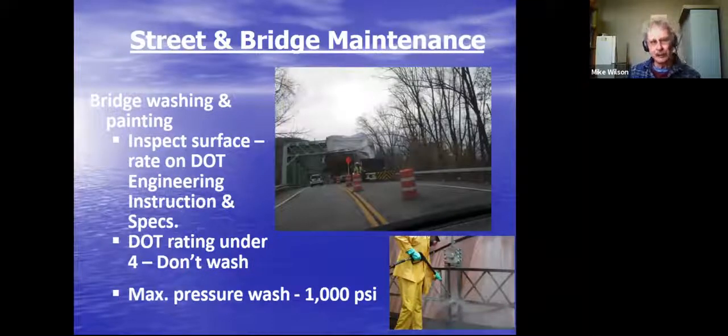Before you wash a bridge or paint a bridge, you have to inspect that surface. And it's rated on a DOT engineering instruction and spec sheet. And of course, you should have an engineer do this. And if it has a DOT rating under 4, do not wash that bridge. Washing it can impair that bridge and weaken that bridge. So anything under a DOT rating of 4, do not wash.